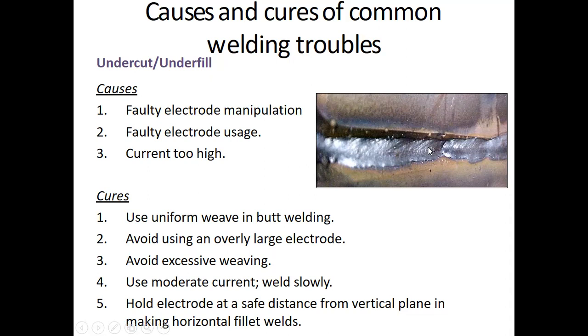If it is movement of the workpiece, if it is movement of the electrode, it depends. Sometimes the electrode is stationary and the workpiece moves. So you have to have a manipulation of the electrode properly. You should be able to move it as much as you want, as exactly as you want. You should have control over this electrode movement.